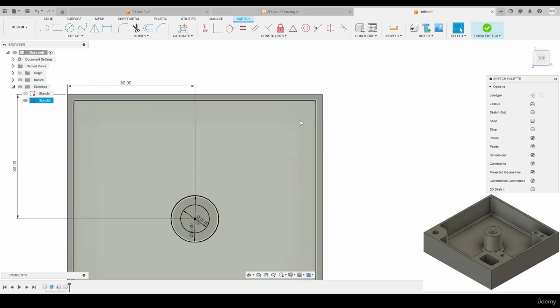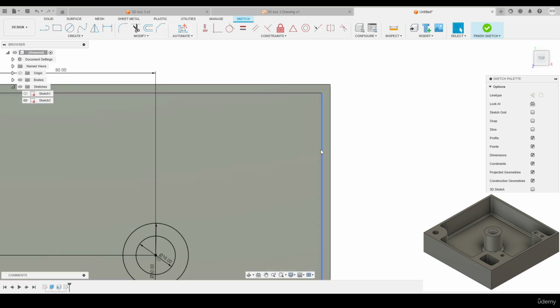Let's come over to this feature up here. So there's a wall that protrudes out with two holes in. Let's go on the line tool. We'll start at the edge here. Come across, down, join that back. Put in some dimensions. The thickness here, I'm going to reference that dimension from this line to this outer edge, 34 mil. We've got a height of that of 15 mil. And then from this line here to the outer horizontal edge, we've got 20 mil.